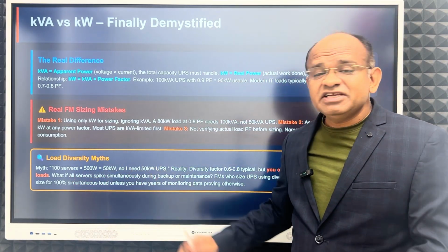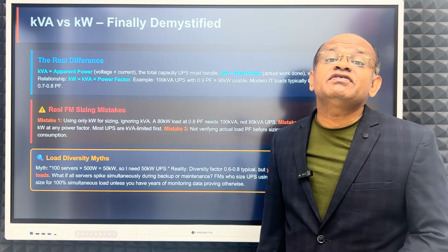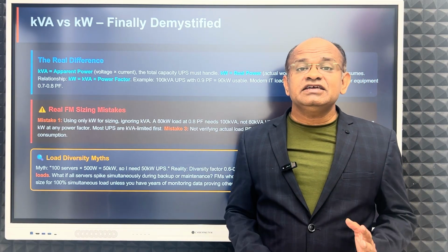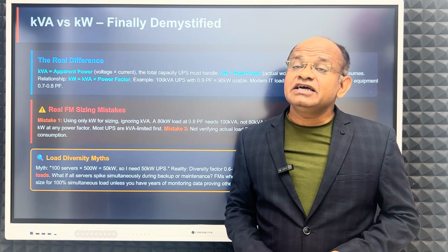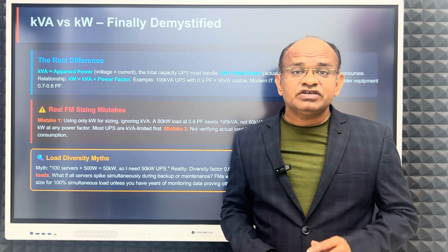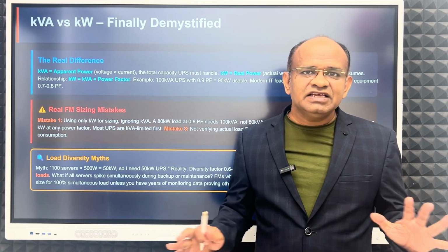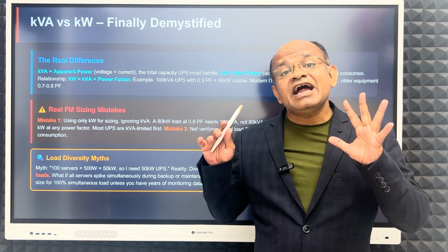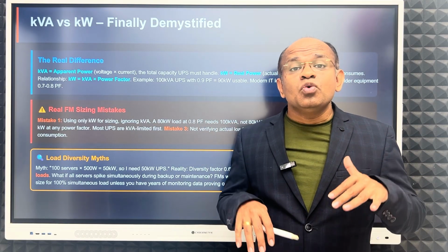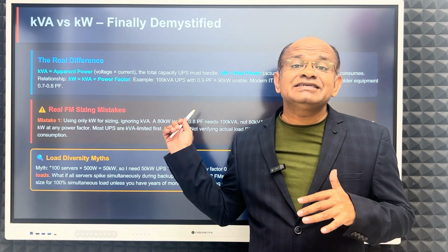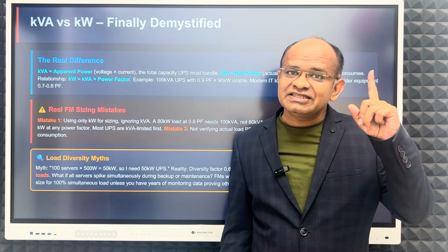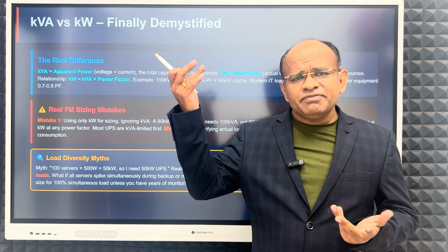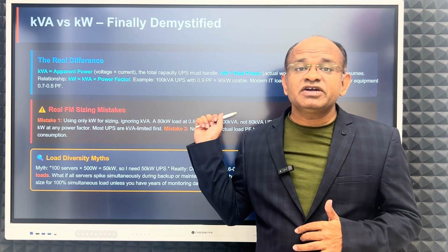Load diversity myths. Now what is load diversity? Let us say I have this television screen, this air conditioner, lighting, everything is there, but I am not using all of it at the same time. When I am not recording this lecture, I am not using this lighting; maybe I will be using air conditioning but not the screen.